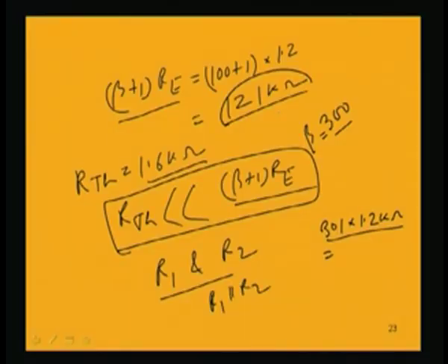So again the operating point shifts, but the effect of beta change is still very dominant compared to that IC naught change, and that is why we are mainly focusing on the change of IC due to beta.